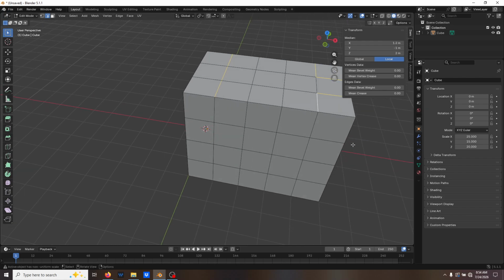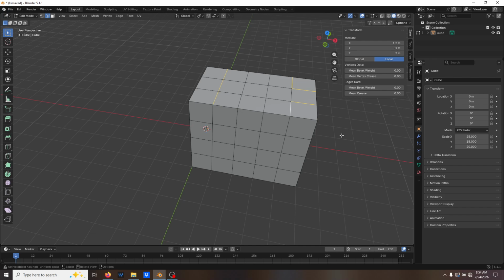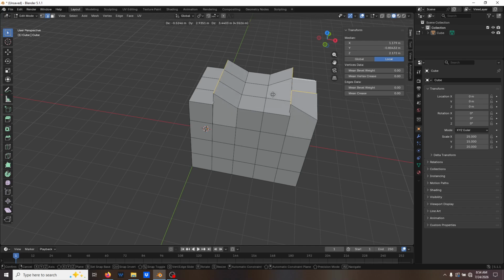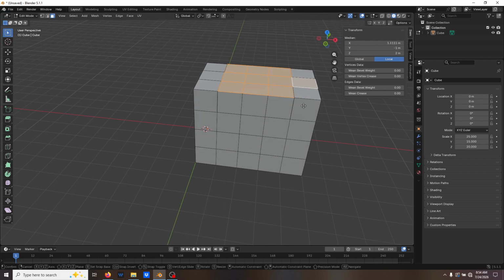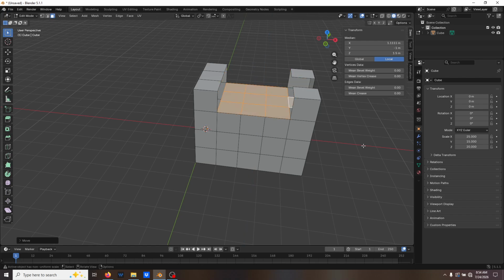All right. And what the rip tool, the short key is V, is going to do, when I press V, it's going to rip, and it actually separates the mesh at those places, right? So now what I can do is I can go back into my face mode here. I'll just select all of these. I can grab those faces, grab Z, -10. There we go, and then it just pulls them.